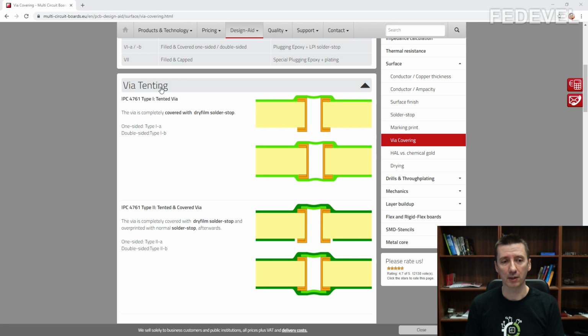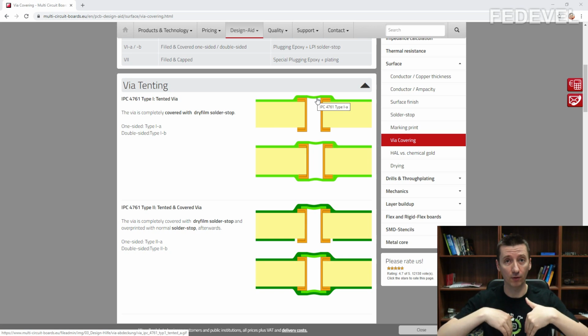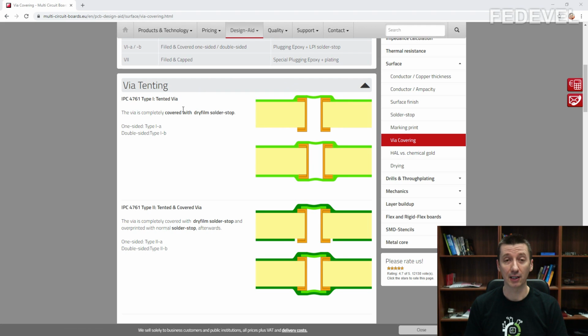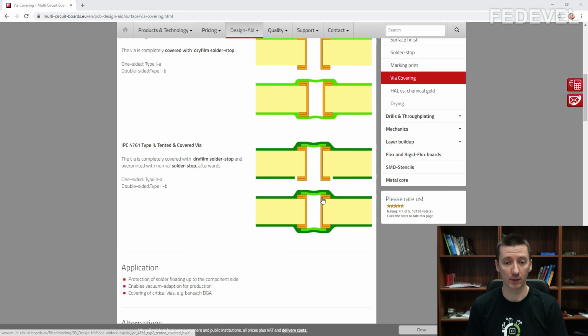And because I always do it, I heard some people actually create a small hole on the top of the via so the solder can flow inside of the via. And I wanted to know if they do this automatically in the PCB manufacturing factory, or if engineers have to do it to be sure that there will be nothing trapped inside of the via.